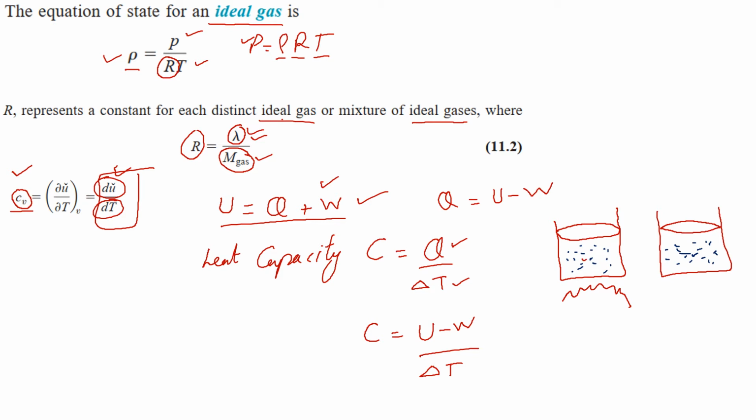And what we do for our initial case, for this case one, we see that the piston is not moving. The piston is closed shut, it is welded shut, and the cylinder is not moving. So what will happen? Only the heat content of this gas inside this cylinder will change. So only this variable in this equation will change, and due to this assumption that the piston is welded shut and not moving, no work will be done in this scenario, and this term in this equation will be 0.